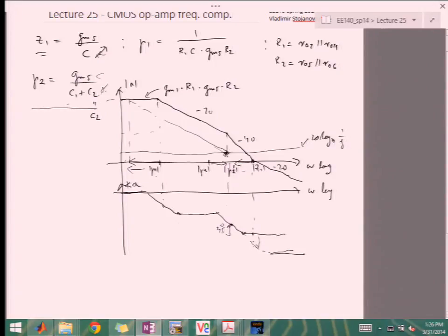45 is good. If I do it a little bit sooner, before that, I may get 60, which is a really nice phase margin. Okay? The problem is that if you're ignoring the 0, as it starts coming down, it starts getting this slope from 90 degrees per decade to something like 180 degrees per decade, right?